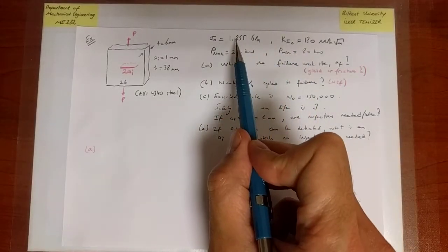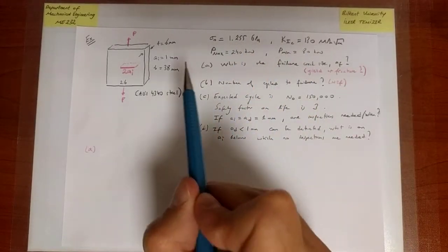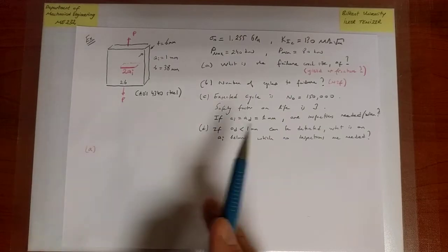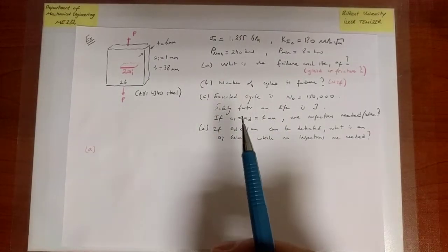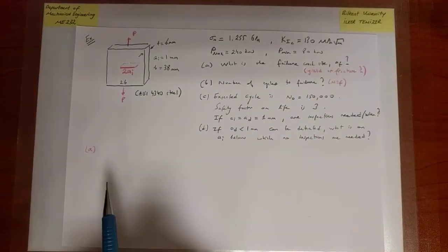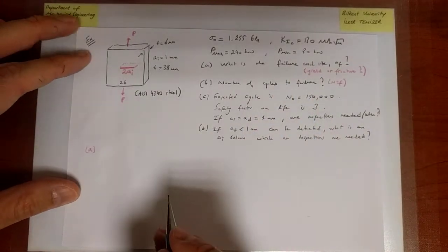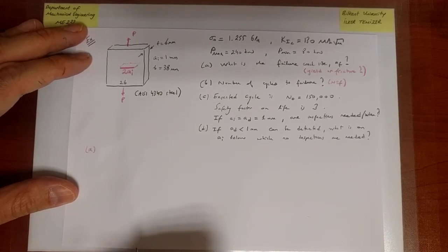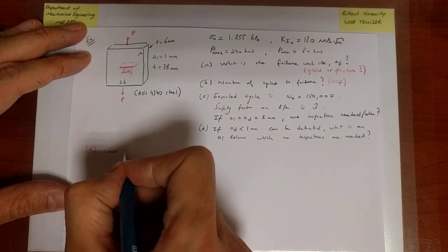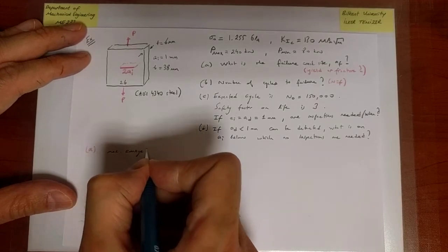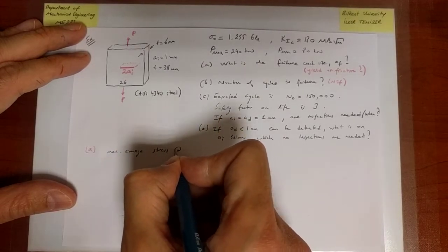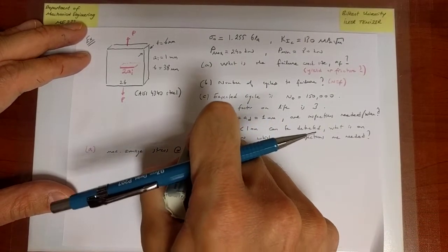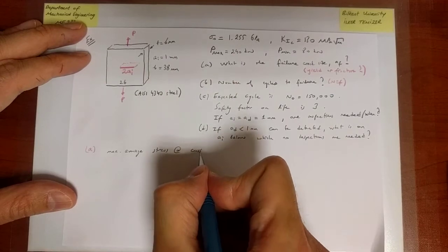And I see two parameters here, the yield strength and the fracture toughness. So the crack will grow over time and eventually it will reach a value at which first yielding or fracture might happen. Whichever happens first will be the critical value of the crack size, which I will deem to be the failure crack size, the final value, AF. So first I will go ahead and calculate the maximum average stress at the cross section where the crack is present.